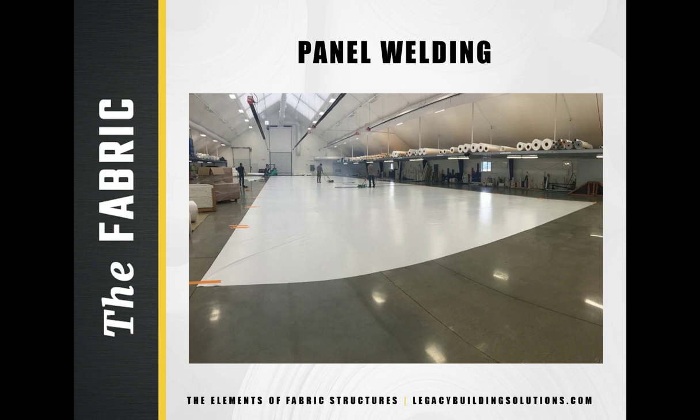Once the panels are cut and aligned, individual pieces of fabric are welded together using hot air, wedge, or RF welding systems. The strength of the fabric weld should be the same as the strength of the fabric itself. Once the fabric panels are manufactured, they can be rolled and packed for shipping to the building location.